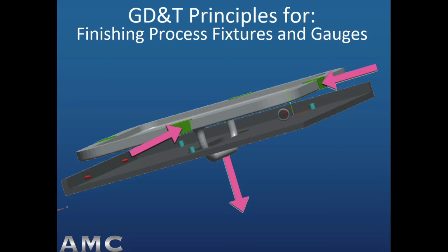This single pin is over here on datum C, and so if you push this casting against the datum B pins and push it against the datum C pin and pull it down onto the datum A targets here, and it sits reliably flat as you do that, without gaps on datum B and without a gap on datum C, then it is a casting that is going to assemble correctly. If it's machined, it'll sit into the machining fixture correctly, and it's okay then to proceed with the grinding operation or whatever the functional gauge is intended for to hold the casting for finishing processing.